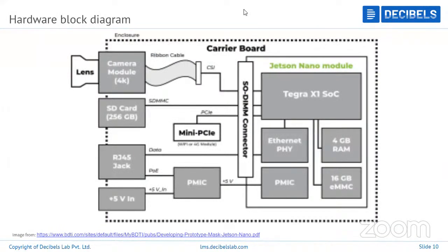Then with respect to your Jetson board interfaces, first of all, your power input. Your CPU or any hardware device requires power, so we would take in power as an input. In terms of power, we get 5 volts as an input. We use either a jack or a PMIC input, and based on that, we get a power input.